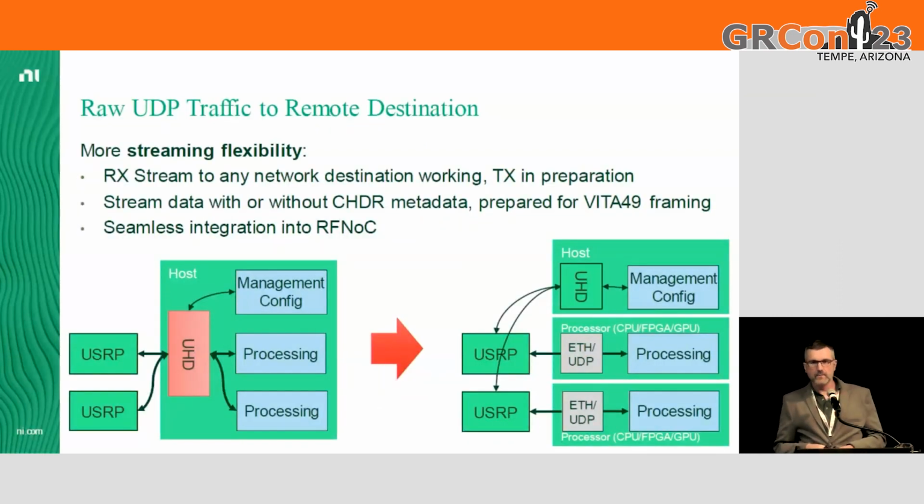Now in the past, whenever you were streaming data from a USRP, all the streaming data went through the same UHD session that also set up your frequency, your gains, antenna ports, whatever else you need to configure. And we've changed UHD, so you don't have to do that if you don't want to. If you think that you can handle the streaming better elsewhere and within your own software,